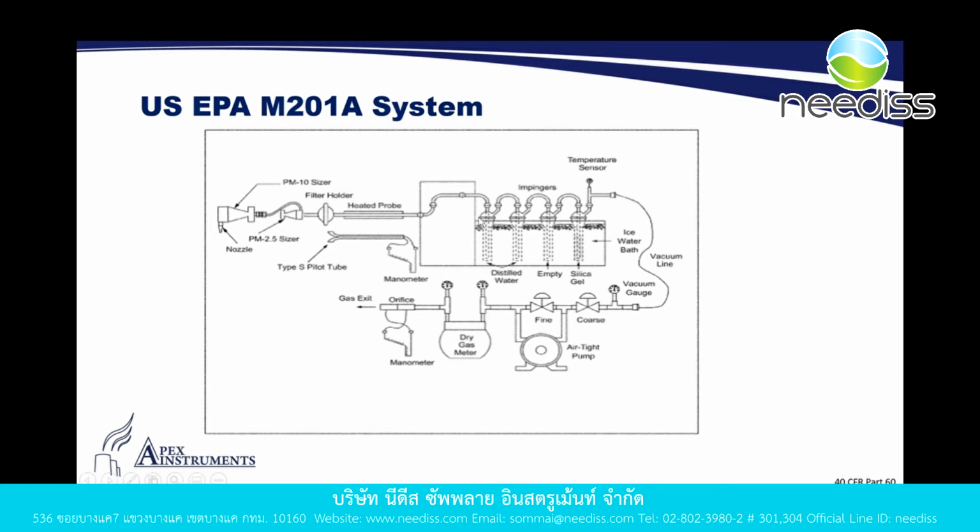You would come to your first impinger. Theoretically, this box will not be here. That would be used for your Method 5, so you're going to bypass that. You're going to go straight into your first impinger. You would have a very similar impinger setup to your basic Method 5, with the first impinger being empty,